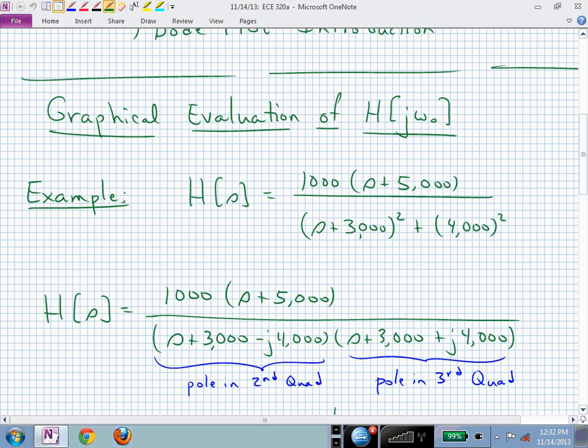That basically says, given this system, which in our case a lot of times is a circuit, you could think of it as a filter, given this filter, how is it going to behave at a particular frequency? And we're calling that frequency omega naught. Last time we had this transfer function, or this system, it has 2 complex poles, it has 1 real zero, and it has some DC gain associated with it.